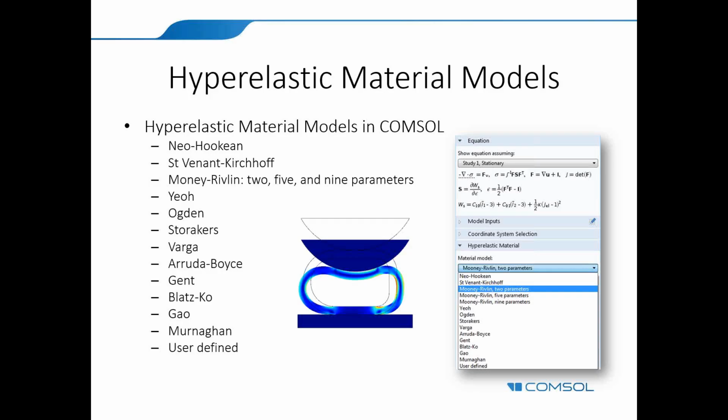In those cases, the strain definition is actually quadratic in nature. So whenever you model hyperelasticity, you have to have that definition of strain in the hyperelastic material model, and not the linear definition that you normally use for small deformation in linear elasticity. When you do modeling in COMSOL, that is automatically checked. So you automatically incorporate geometric nonlinearity, and you don't have to do anything extra to include it.